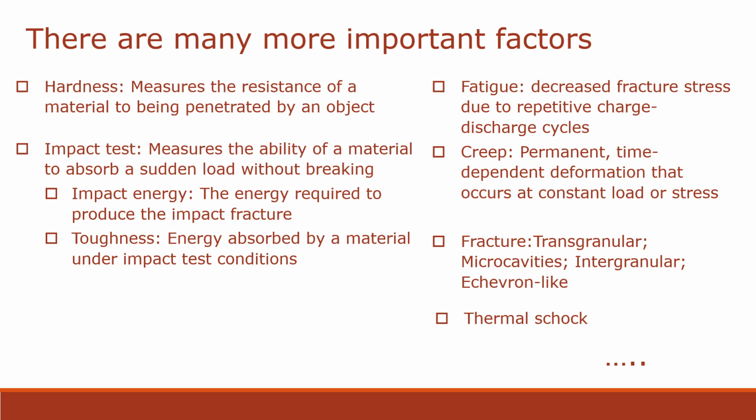So that means a lot of fatigue, but also because the wings are quite long, and so when the plane is flying, they are vibrating, and this vibrational movement is cyclic, and so it means that they are going to be submitted to repetitive charge-discharge or load and unload cycles. And this is very important because fatigue problems can lead to what is called catastrophic failure.